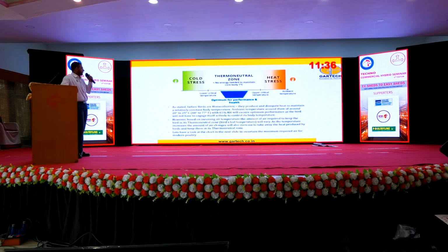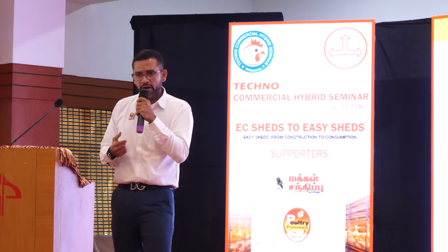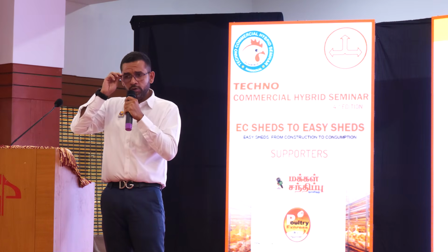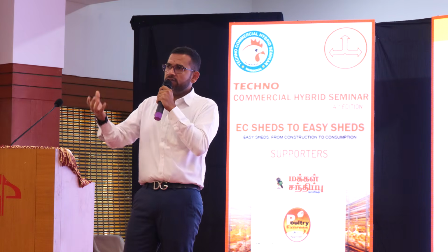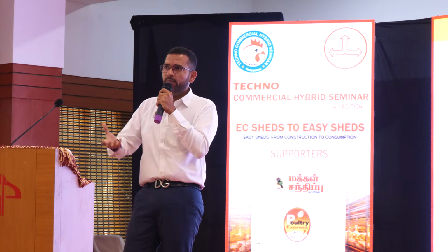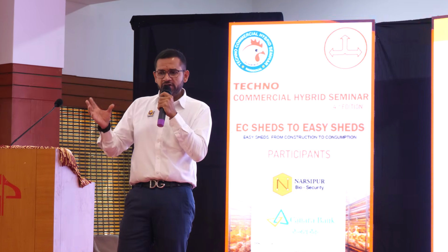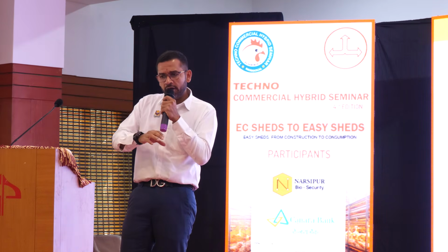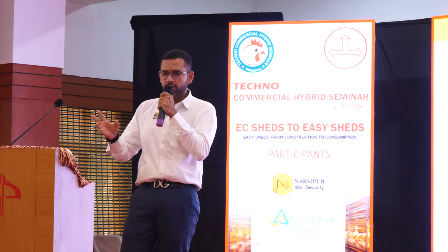As we stated before, the birds are homeothermic. They produce and dissipate heat to maintain a relatively constant body temperature. Based on the incoming air temperature, the amount of air required to keep the bird in its thermoneutral zone is always going to change. So this is not just the temperature of the air, but also the relative humidity in its surroundings. As the temperature increases, the amount of air changes will also increase to take away the heat produced by the birds and to keep them in their thermoneutral zone.